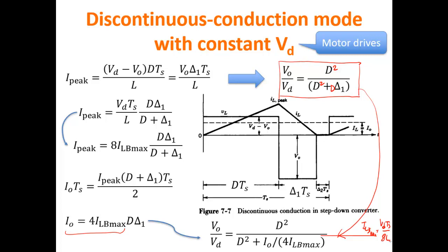Since the transmitter typically has integrated on the same chip also a receiver, you have the same power supply for both. When the current absorbed by the transmitter changes so rapidly, if the system is not extremely fast in changing the duty cycle to keep the supply voltage constant, you have a huge change in the supply voltage of the receiver, and therefore a significant disturbance in the receiver, and typically very poor performance of the radio part.